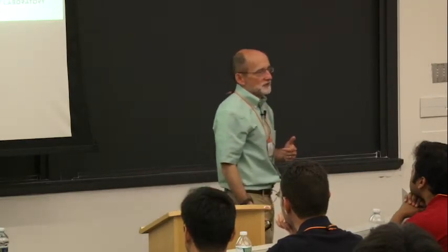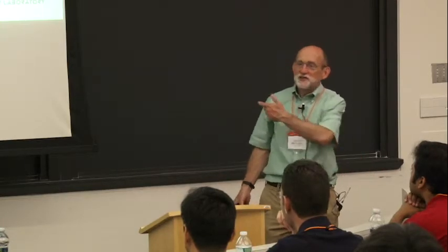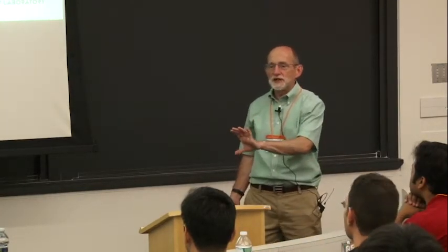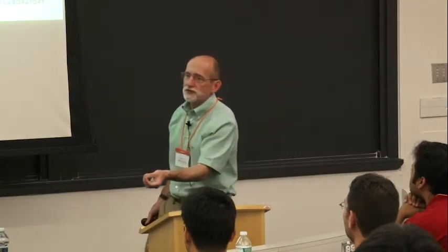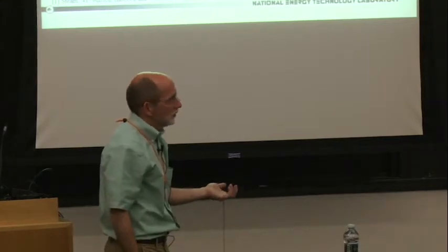Well, if I'm worried about the kinetics in my chemical looping system, if they're not fast enough, guess what? I don't need 2% of them then. I can put in a lot of them and I can really jack up the reaction rate because I can put more material in there. And it isn't always appreciated. People think, well, how can you do this chemical looping when you've got to react this solid metal? Isn't it too slow? Well, it might be, but I'm trying to tell you it probably isn't and doesn't have to be because I can load it up with a lot of that material.